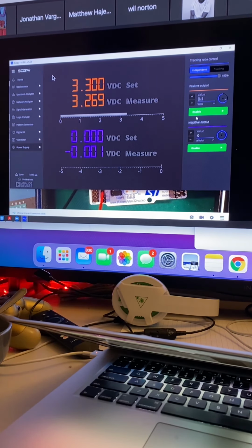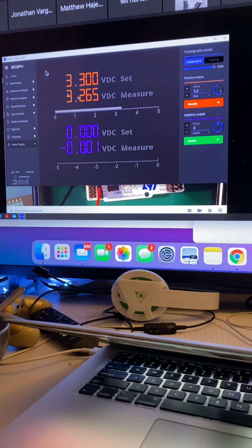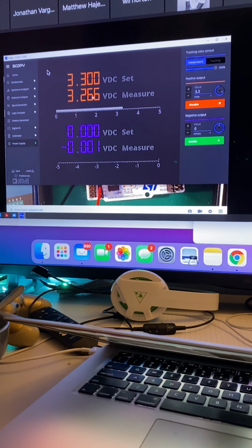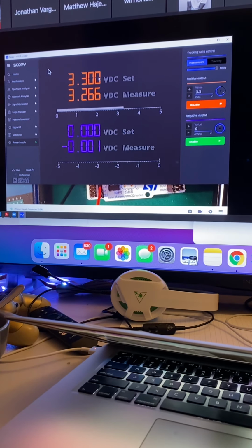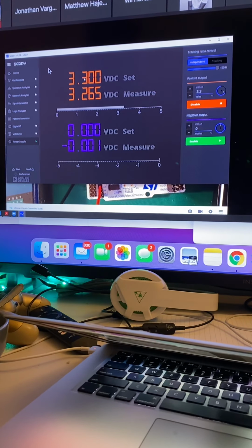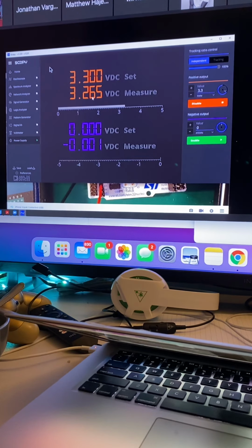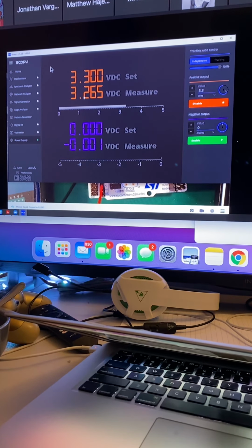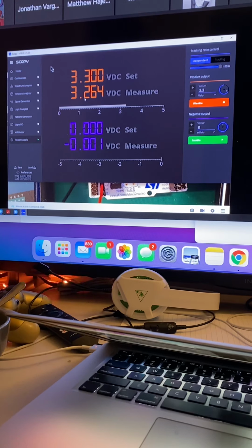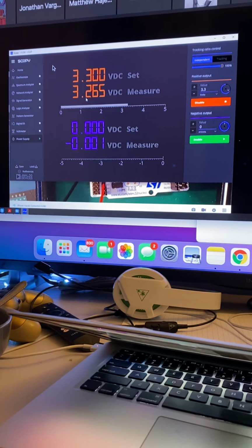Now, when you enable it, that's when it will actually start generating the voltage at the output. And you can see now, this guy has started changing a little bit. We've asked for 3.3. It's giving us 3.26. That's as good as it gets. Don't play around with the nominal voltage here, trying to get the measured voltage, right? Just set a nominal voltage and make note of what the actual measured voltage is. This is the voltage that it thinks it's applying onto your PA4 pin. So that's what you're converting, right? You asked for 3.3, it gave you 3.26. Go with the 3.26, okay?